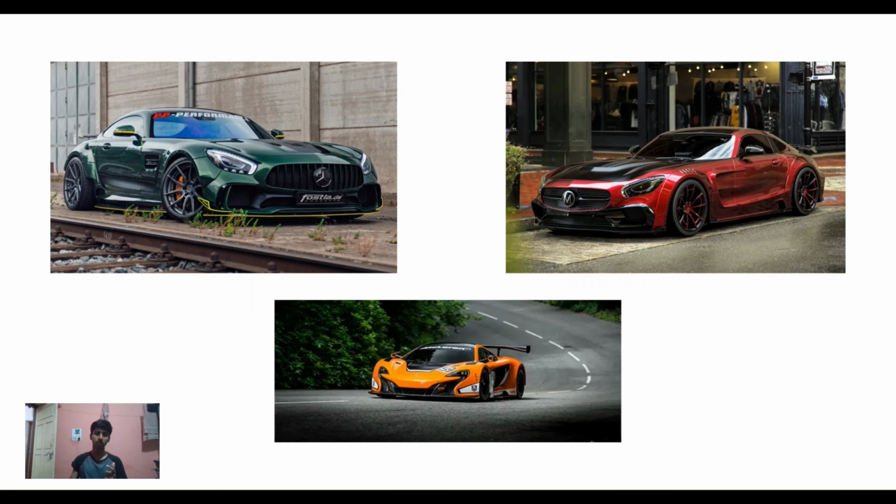Now, track width not only gives that aesthetic look, but there are also technical reasons for having wider track widths. Always aim for a wider track width. The larger the better. The only consideration comes in when you are taking packaging or transportation into consideration. Say when you have to load your car into a trailer and the trailer is only this wide while your track width is this wide, it does not help. Also take into consideration how much limit you have as per your SAE or ESVC rules, how wide your body can be.